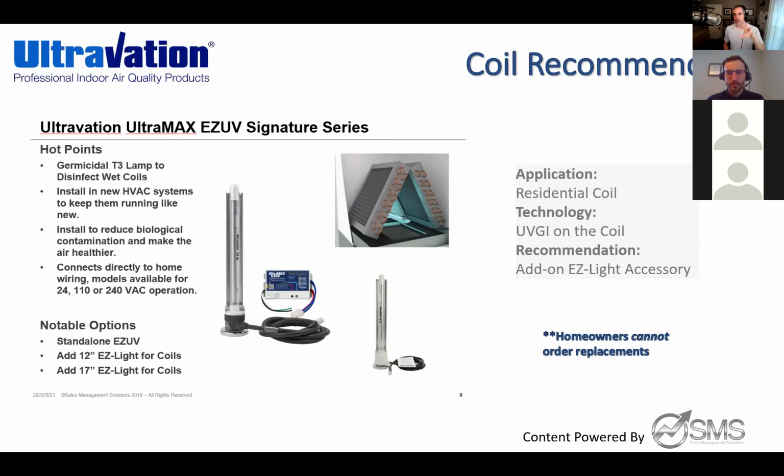The Advantage is a throwaway product. You take the same two screws out, but it's an entire module. You take the whole module and the bulb out because it's glued to each other. It's not an interchangeable lamp system like this is. That's why that product is always in warranty, because literally the wiring, everything gets removed. Whereas this power module stays mounted on my system, and it's got a lamp monitoring light on it too. So I would get a nice alert if for some reason the lamp would fail. So that's the advantage of going to the higher lifetime warranty model like this.